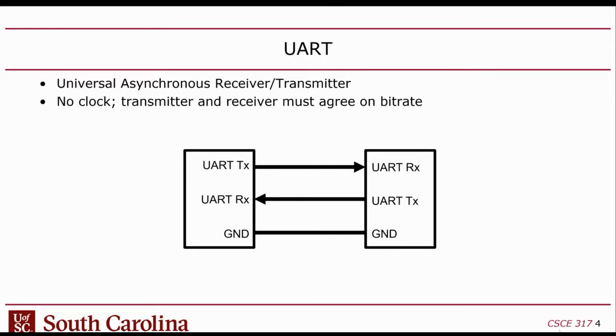As I mentioned with UART, they have to agree on a bit rate. This is a constant headache if you've ever had to plug a terminal into any kind of piece of gear, because you never know what the bit rate is. So it's basically a guessing game. If I connect my laptop to a piece of laboratory equipment, you could look up the bit rate in the manual, but who does that? Generally, it's trial and error. You try all the different speeds until one of them works. So that's generally how UART works.